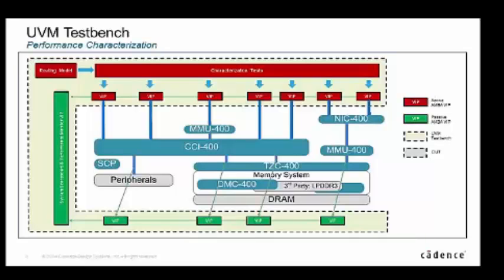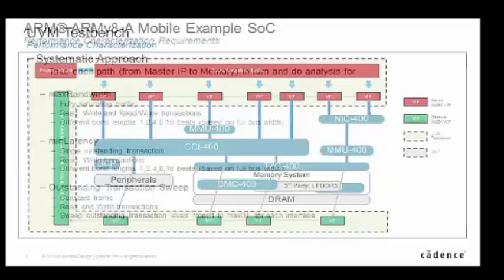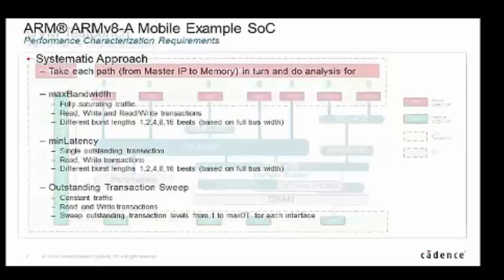And the middle row is latency over time. For write transactions, they're straight lines. It's utterly predictable. Well, writes are posted, so it always happens instantly. For the reads, it's a round-trip delay, and there's variability in this.